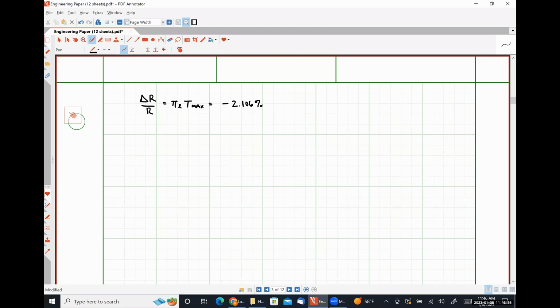So that 25 micronewton force causes roughly a 2% change in the resistance of each of the piezoresistors, right? It should be the same for the overall piezoresistance anyway, though, since they're just both in series.